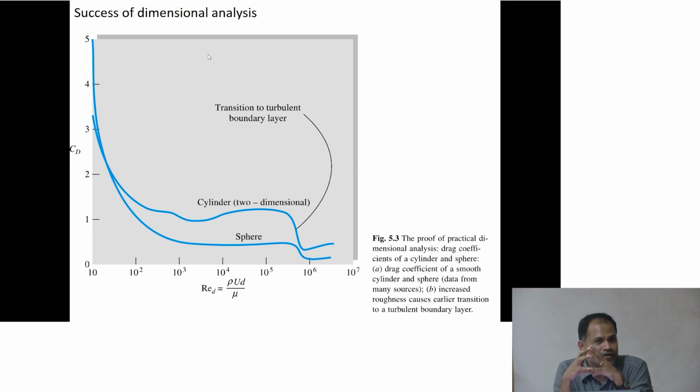Okay, and we know that you can calculate the force exerted by that object simply as a function of Reynolds number, and what you see is essentially that graph. On the left hand side, it's called the drag coefficient. It's the force. So it's that drag force that we calculated over rho u square L square, versus Reynolds number.